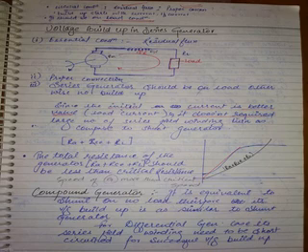In a series machine, the initial current is coming because you are loading the machine. It is not simply coming like this. Some voltage is developed in the armature, and that voltage produces the current. You are making some load, so you are reducing the resistance of the path. What is the resistance here? Very huge, so a small current. By reducing the resistance of the path, the initial current is very high, in the sense that compared to this, the current here is a good value. So when the initial current value is very good, there is no need for a large number of turns. And as you start loading the machine, the current value will automatically increase.